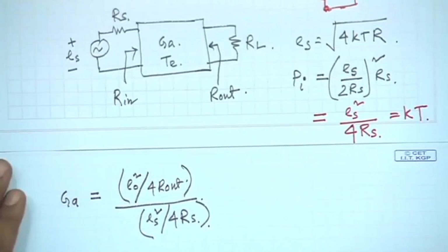So, one interesting thing about the gain: for any amplifier, if we want to calculate the overall gain, it might seem to depend on RL, but when we ask what is the gain of an amplifier, we do not consider RL; we take just the open circuited output voltage and then calculate the gain of the amplifier.